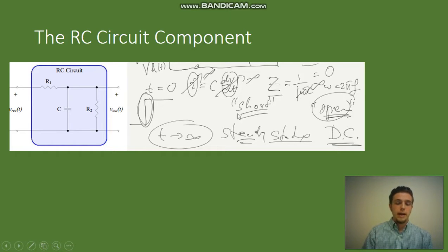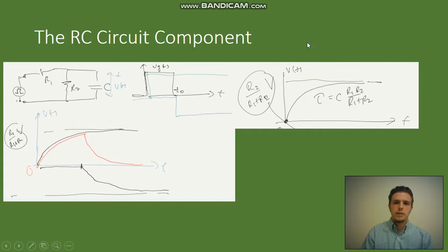shorting the capacitor again. And if we look as the capacitor charges over time, as t goes to infinity, in this graph of your time constant, tau equals C times R, and that R is what is seen by the capacitor as it charges up, and at this value, say infinity, your current is 0, because the slope of this derivative at any point will be 0.